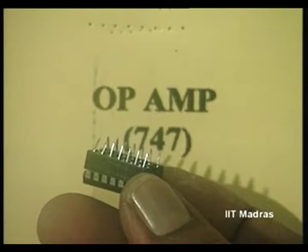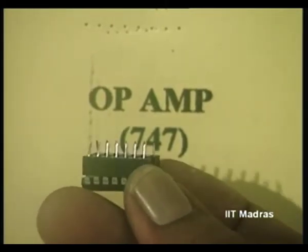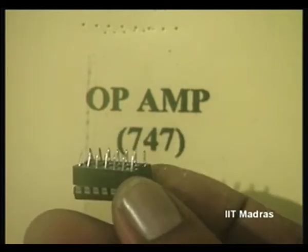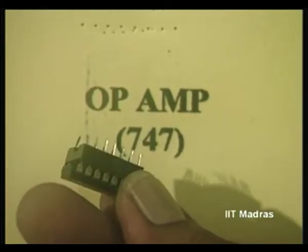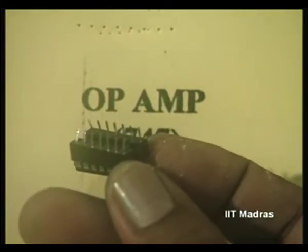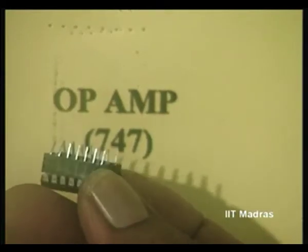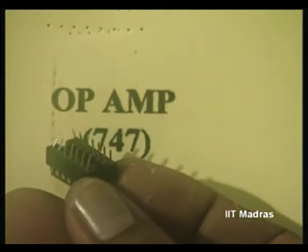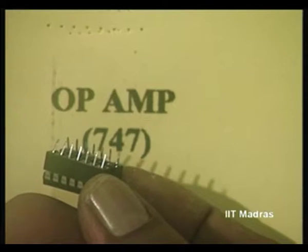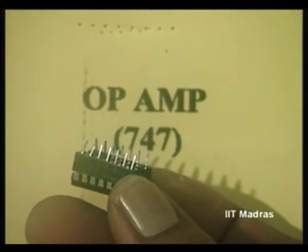So 2 plus 1, 3 plus 2, 5 terminals essentially, and with 2 such op amps we have 10 terminals taken care of. In this 14 pin package we have the possibility of what is called offset compensation, about which we have also discussed. So 2 terminals for one op amp and 2 terminals for the other op amp for offset compensation.